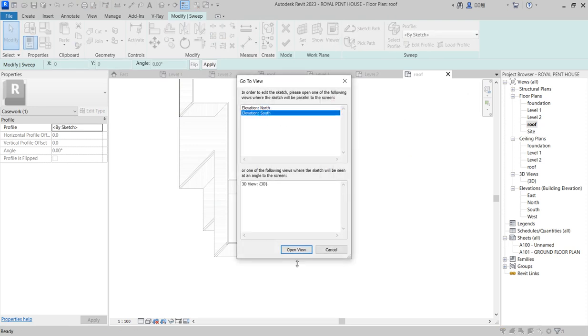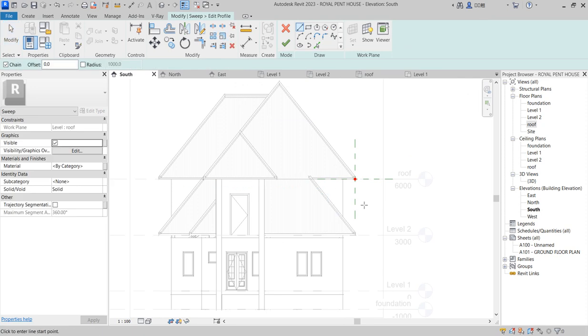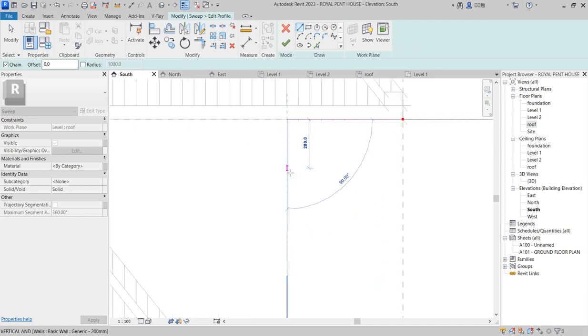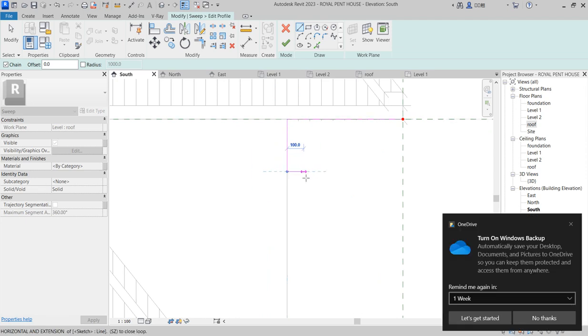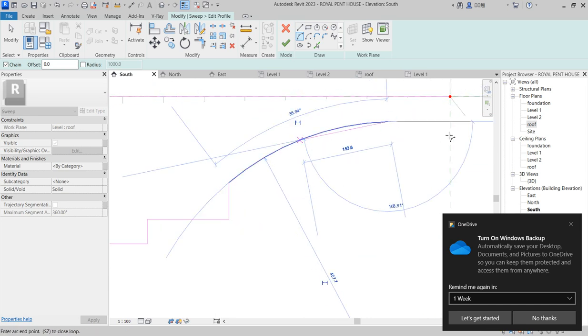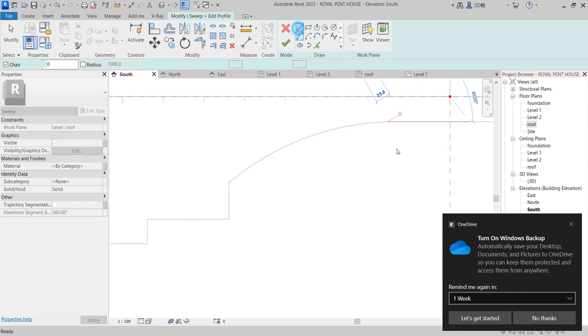So I'm going to edit the profile from here now. What I do here is that from here I draw my first line. You can drag it inside if you want, when you know the boundaries of that one, but later you can do that when you are doing the section and cut stuff. So you do this one by 300. I'm creating this in place, creating this, and then creating this. I'm going to give this one opportunity of arc. So it's going to be here. I'm dragging the same method.